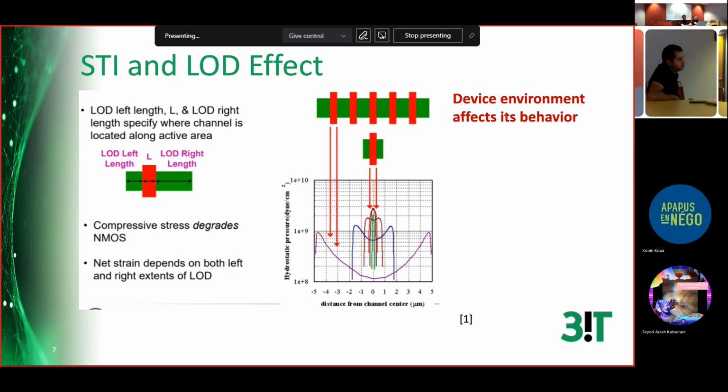And this is the picture after mechanical simulation, the contour of the stress. Exactly. So the STI here, mechanically, the structure of the CMOS makes you have mechanical stress on the edge. You have mechanical stress everywhere, in fact. But if you look here, you consider the two edges, the STI here and here.